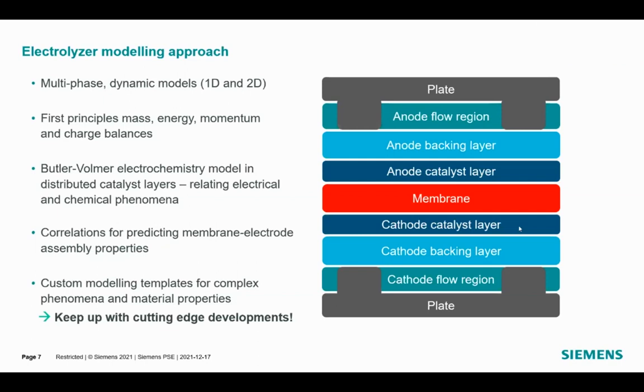And we model this equipment using multiphase dynamic models that take as much advantage as possible of first principles of chemical engineering to do mass, energy, momentum, and charge balances, as well as a lot of literature information to model the electrochemistry that happens in the membrane electrode assembly. A lot of this, due to the complexity of the materials, is based on correlations that are fit to experimental data.